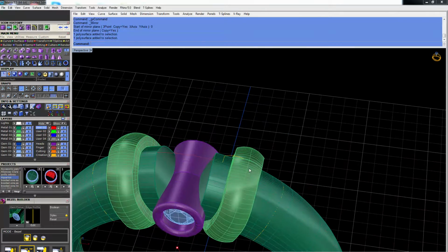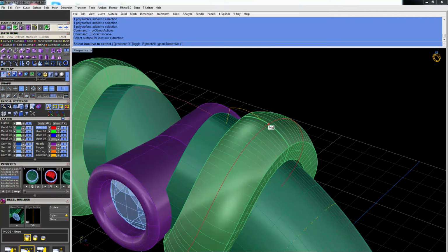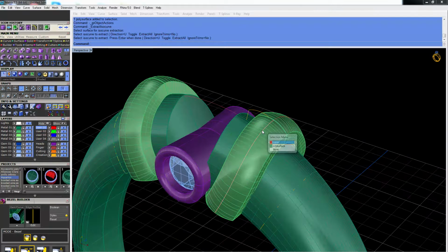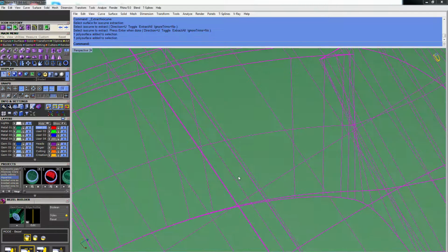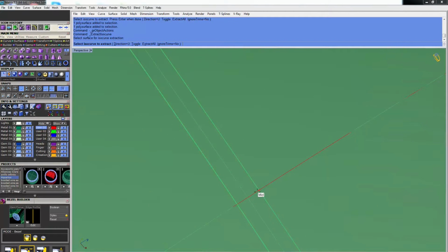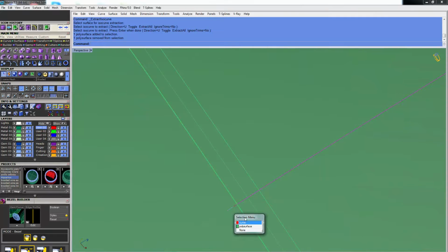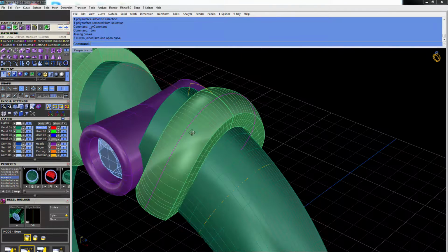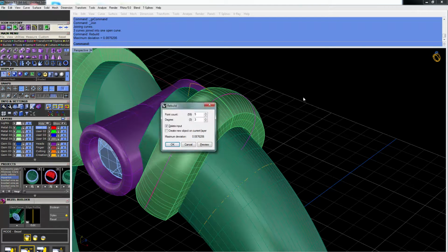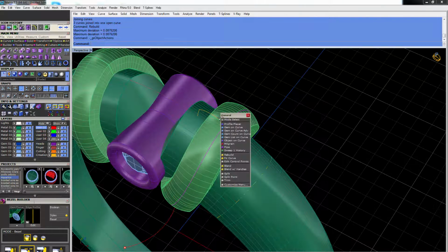Okay, oh well, I forgot about this. Click on that object, F6, extract isocurve, because we want to put gems in there. So I created a line in there, and now if I select that line, hang on, and that line, doesn't matter, extract isocurve here and join it, so we have one single line. Okay, that's a line. Actually we should click on rebuild just to make the curve smoother. Okay, it looks slightly off center, but it's not going to make a massive difference.